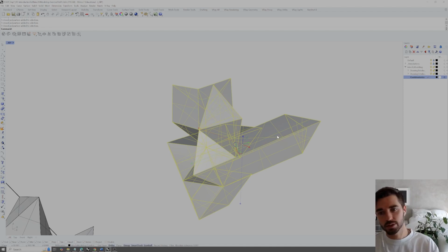So we can do this unwrapping procedure by typing Unroll Surface, and this is going to work with any singly curved or planar geometry, meaning it doesn't have 2 axes of curvature. So we'll talk about this in a bit, but this is going to essentially rule out most of our swept geometries if we have 2 axes of curvature there. So if our profile or sweep sections and sweep rail both have curvature, then that's not going to be eligible for this type of operation.